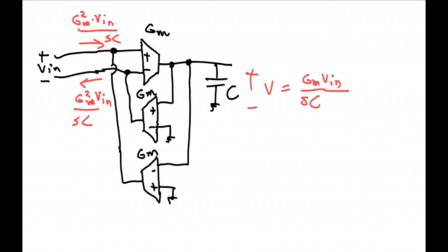So now we can see that what happens at the input side here is that the current is the integral of the voltage. So if you have a component in which the current is the integral of the voltage, well, what do we call that component? An inductor. Oh, isn't that fantastic?